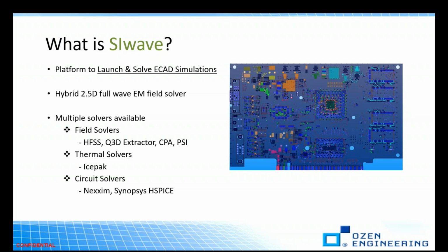So what is SIwave? It's an electromagnetic based software solution for power ground plane and signal integrity analysis. It employs a powerful full wave analysis engine to generate both frequency domain and time domain results using the highly optimized internal field solver. SIwave simulates complete board package design with full wave accuracy. Simulation results can be reported graphically using advanced 2D and 3D plotting methods.